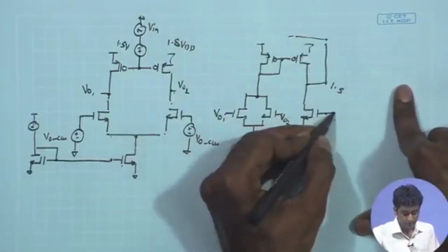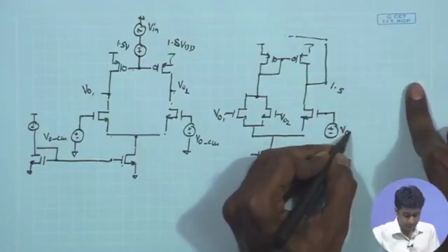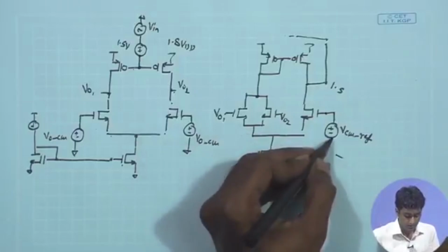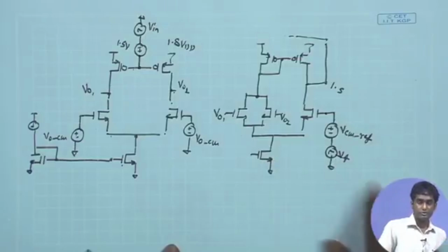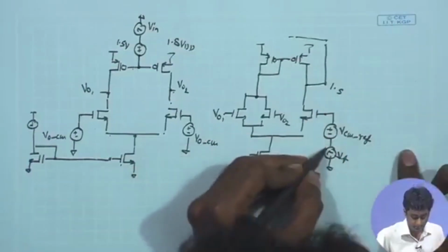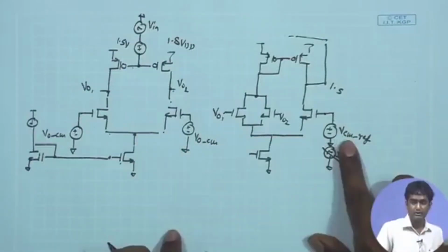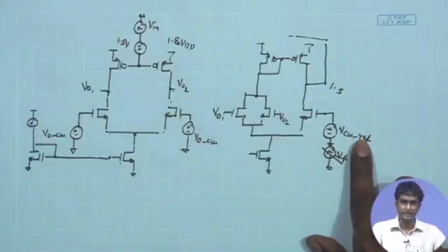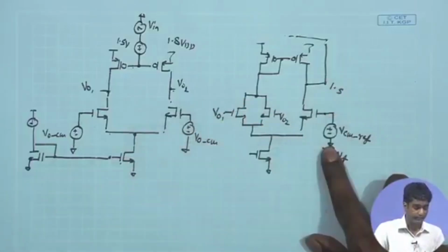And of course, here we also need to keep the same Vref, I would say VCM ref, that we had under the normal closed loop operation, and then apply an AC signal on the top of that, Vtest if you call it. So, this is the test signal, the AC signal. Sorry, in this case we are not applying the test signal over here, but we just need to put it at the required VCM, because in this particular first case, I am assuming that the input signal is applied over here. So, you just need to make sure that this is also at the same VCM ref that you had applied.